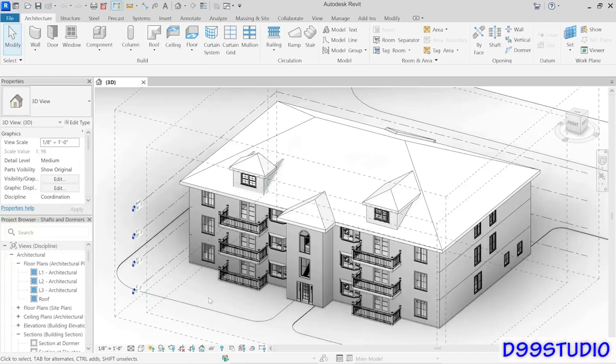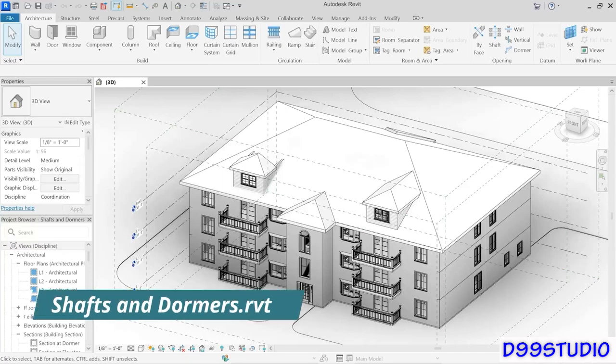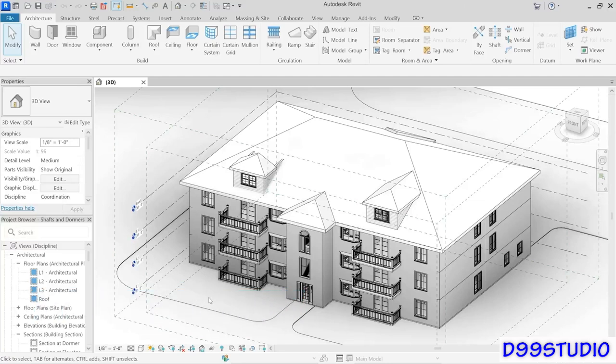Revit has a number of opening elements. They all share one basic characteristic in common. Opening elements are a void element that cuts away from solids. So it's similar to the way doors and windows behave. When you place a door or a window in a wall, it cuts a hole in that wall. So with the opening elements, you're just creating the hole that you want to cut through the object, but you're not filling it with any geometry in that process.